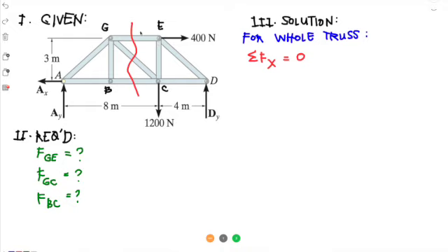So for the direction of AX, if we do a summation forces X, we can see that E is going to the positive X. AX, there are no other X forces, should go the opposite direction. So that is correct. So for AY, this will remain to be an assumption, since if we do summation moments, it doesn't make sense to do it, right?